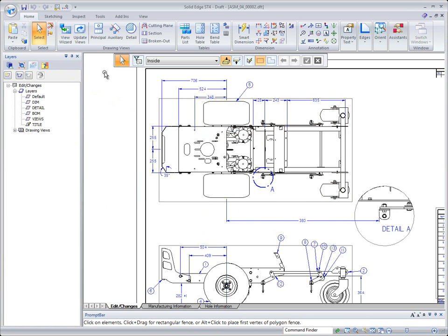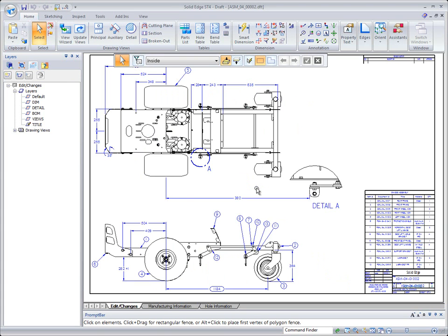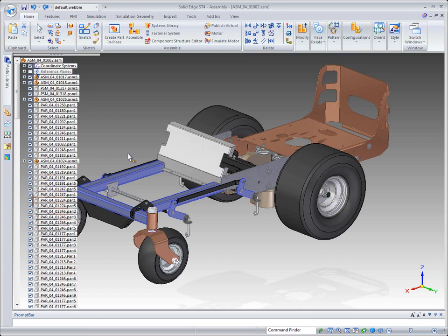to open an editor, and what that'll do is take that View and Markup file and open it back up into Solid Edge. And so once inside of Solid Edge, we can look at all the different variations that we have in our 2D drawing, or we can just simply double left mouse click on any drawing view, and that will open up that part or that assembly in its own native window.